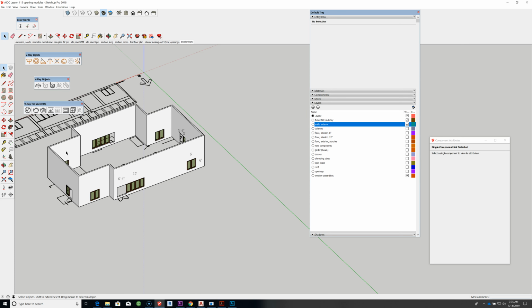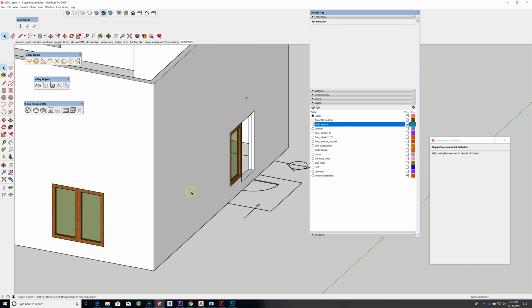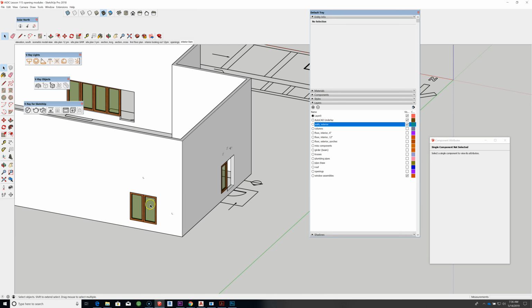Probably beyond the scope of this discussion, but depending on the type of construction, if this were a brick veneer, a lot of that window sill would be to the exterior of the window. It depends on the type of construction. If it's light wood, typically more sill on the interior of the window.